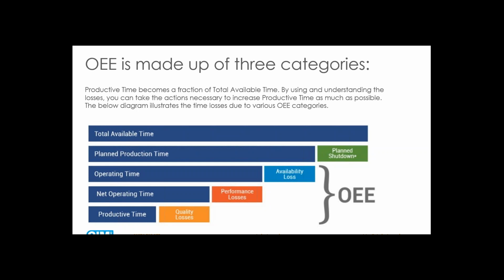That could be, as we say before, that we don't have a shift to run. It might be that it's a bank holiday and we don't produce anything on a bank holiday. We don't have a labour force in. But it's also something that you might want to capture. So what a lot of people tend to do is also do a calculation that includes the planned shutdown that we would call TEEP, or total effective equipment performance, and that would indicate more of a complete capacity utilization. So you have this machinery, you have this plant available to run. It could run on a night shift should you choose to put a night shift on, but the fact that you haven't chosen to put a night shift on is still potentially lost. You've got the assets there available that are able to produce, it's just you're choosing not to use them.